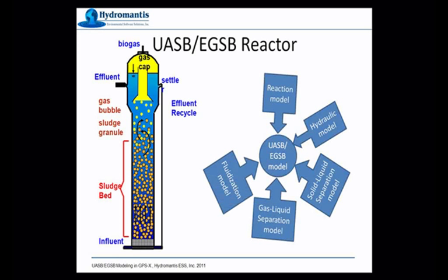Also, to model the solids which are coming out from the reactors and their interrelationship with the sludge blanket height, we need a sludge fluidization model. And finally, since these are granules, we need a kind of substrate transport model to model the biofilm reactions going on. So if we look at all of these modules and try to develop a model, it's a very complex model.